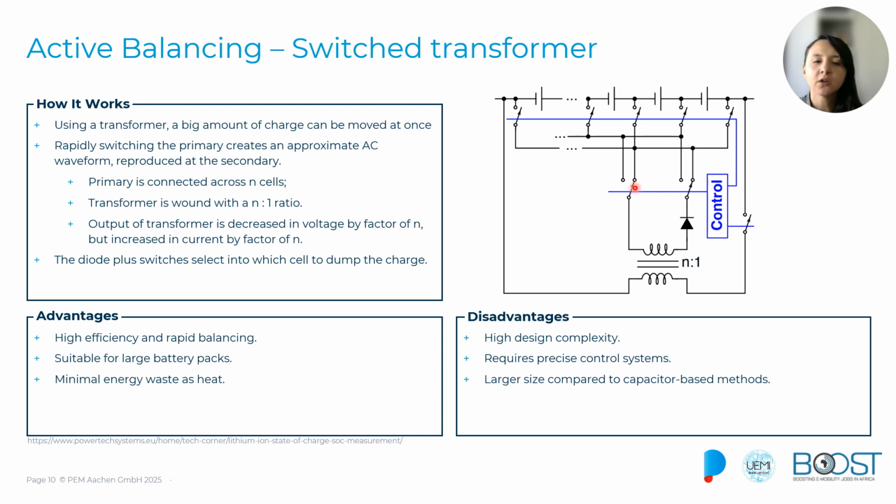With this, we have concluded with all of the balancing methods. Depending on the application and the requirements, again, we can choose which method to use. The passive balancing method that has switched resistance is widely used even in energy storage systems because it's very cost effective, whereas, for instance, these transformer solutions are very efficient for electric vehicles and can be implemented in more demanding applications.